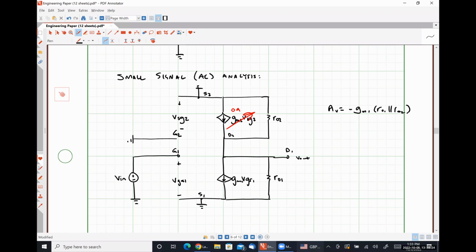That's usually a simple analog voltage divider style circuit, but we have to be very careful about variations in temperature, variations in power supply voltages, and all those kinds of things.